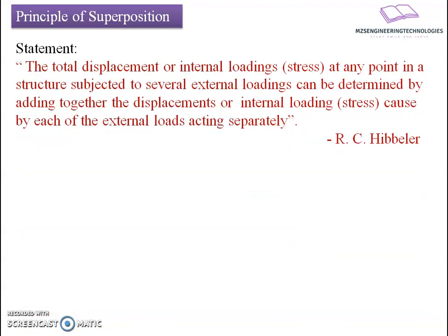The statement states that the total displacement or internal loading, that is stresses, at any point in a structure subjected to several external loadings can be determined by adding together the displacement or internal loading caused by each of the external loads acting separately. It means that if a member is subjected to several external loads, it becomes a complex job to estimate the displacement. In that case we can simplify by separating individual cases, analyzing each individual case, and then summing the effects to find the total displacement of that section. Let us elaborate this with an example.